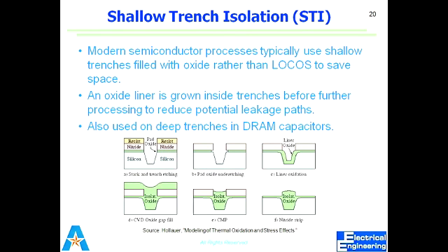So this is the last thing, that is shallow trench. One other method that is used to avoid that bird's beak is shallow trench isolation. In this case, as you can see from here, first of all we drill a trench. After that we etch the underneath oxide, the pad oxide, under etching.